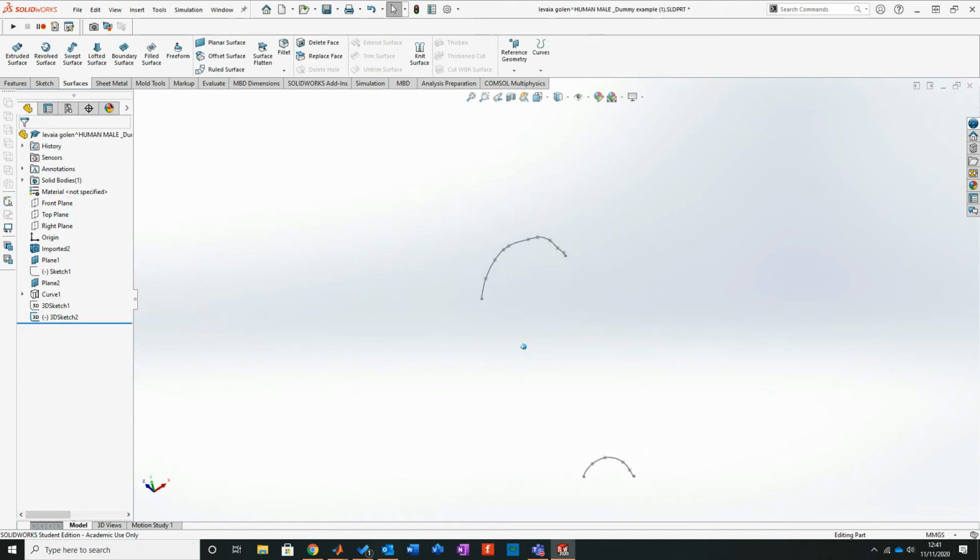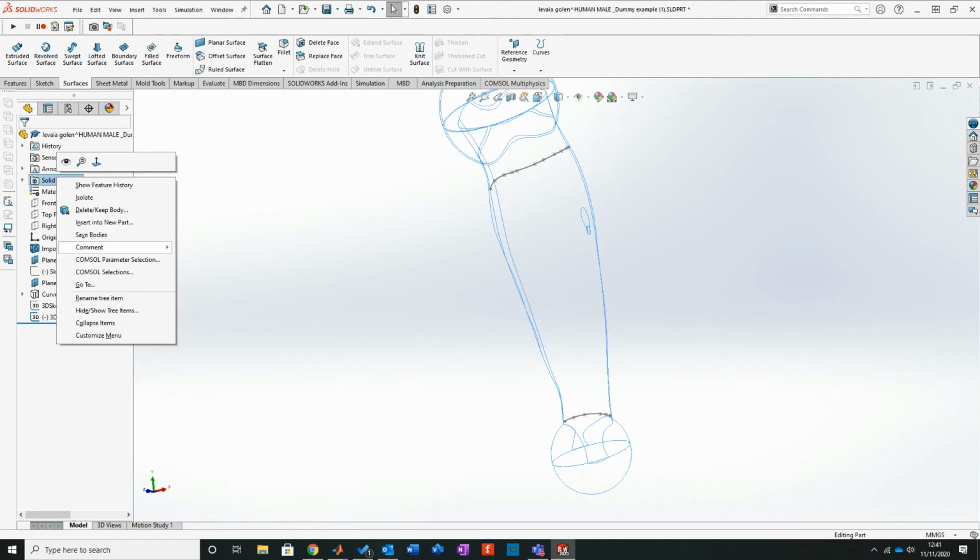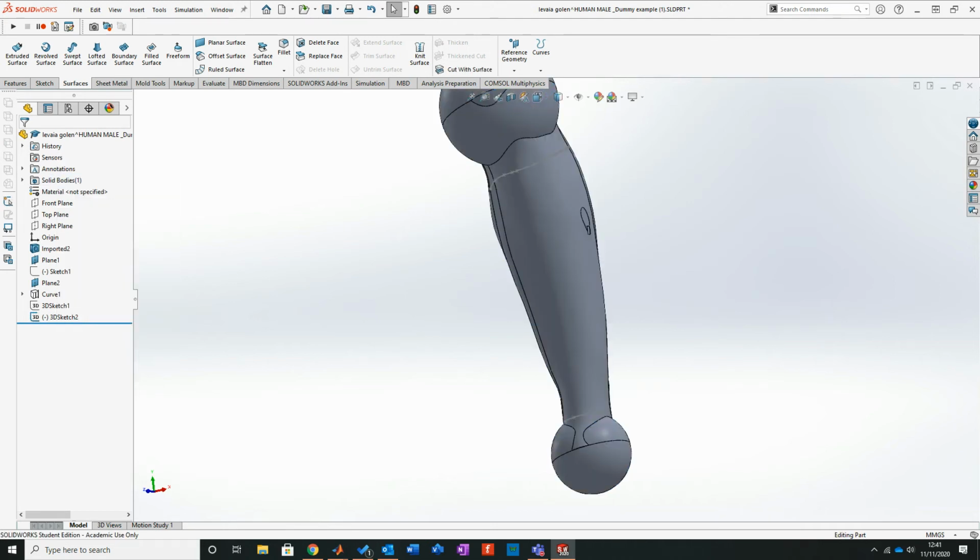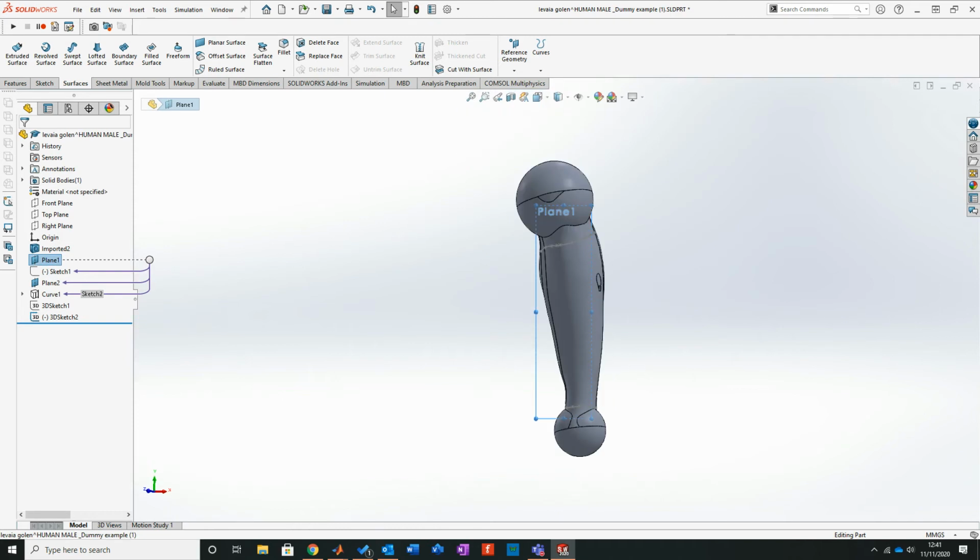What I really want though is I now want them profiles that really create that design of it. So what I'll do again is bring back in my body. So show my body. Show the body. It says show my body. It just sounds weird. I'll press Ctrl and 8. That goes normal to view on that profile. And I'm then going to go sketch.